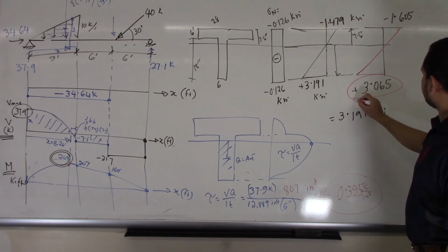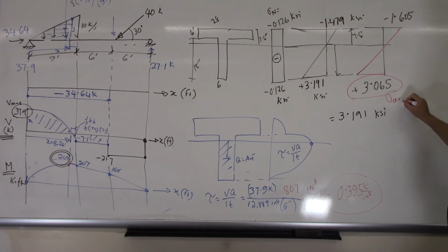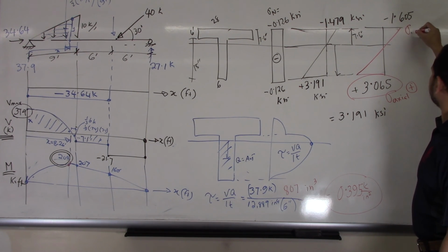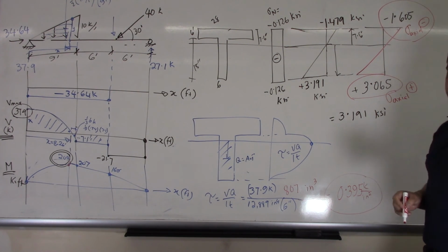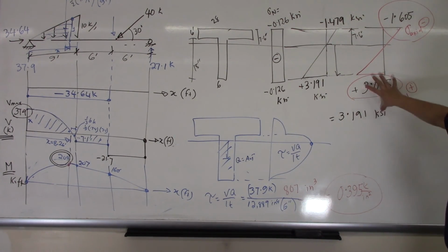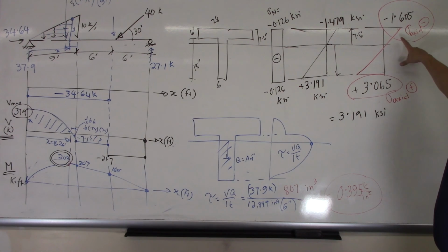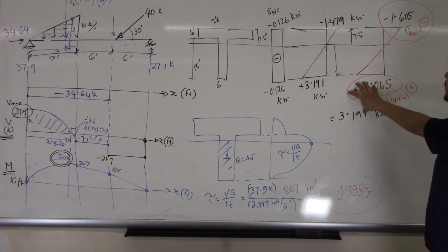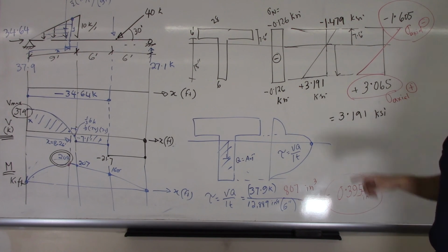Okay, so this is my final maximum axial stress in the tension zone, and this is the maximum axial stress in compression. Actually, both are answered. Ideally, we are concerned about this, not this one, because if the beam can take this amount of stress, it can obviously take this amount of stress too.